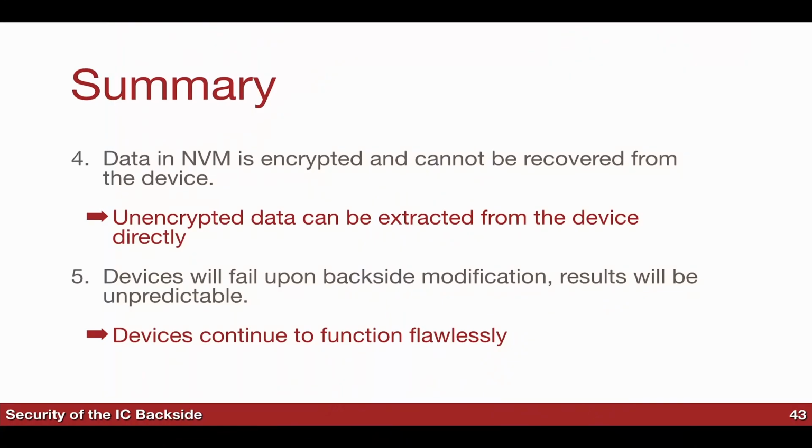And we saw, if it's encrypted, it has to get decrypted for the chip to be able to do anything sensible with it. And the last one, which was my personal favorite, is devices will stop working if you do any kind of backside attacks on them. And the truth is, I can say with 100% of certainty, we've removed 99% of the device, and it still works fine without, literally 99% of the thickness of the backside we've removed, and the device still works. So that's not true at all.